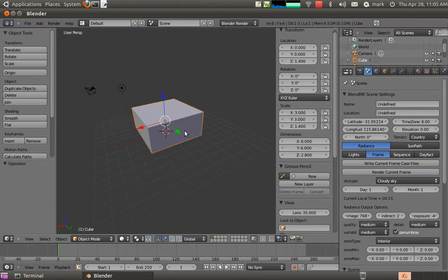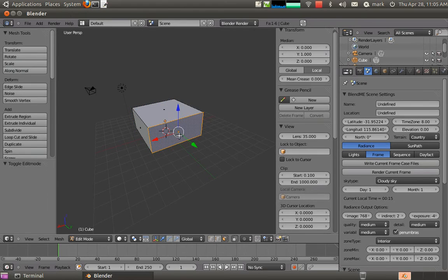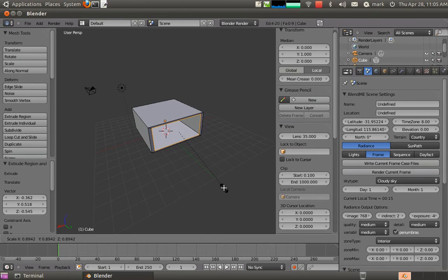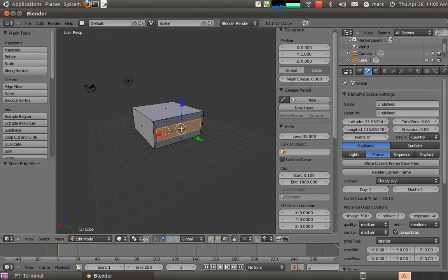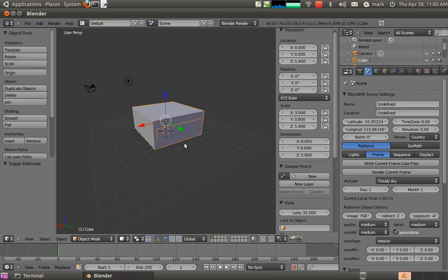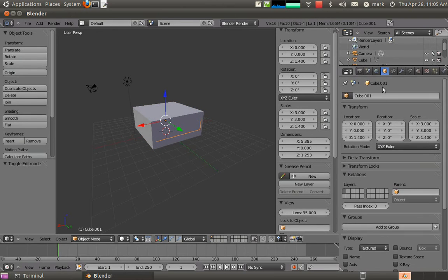On the northern side, I'm just going to put a window. So the way that I'll do that is just delete only the faces. Select the edges, scale them out, and if I scale in the Z direction, I'll just make a thin window just so that we get some nice effects inside. So there we go, a bit like that. Fill that up with a face now, make that face a separate object. Now I've got a window here. I can call that object window if I like, and I can call the other object walls. There we go, walls, there we are.